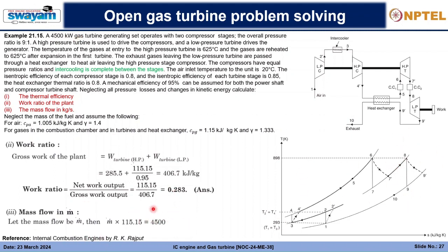If that is the case, then m would be 39.08 kg per second, and that amount of air needs to be supplied to the compressor in order to get that amount of power. We have neglected the mass of the fuel gases, so we need not calculate that because the air-fuel ratio is not given here. But if the ratio had been given, we could calculate more precisely the amount of air required.